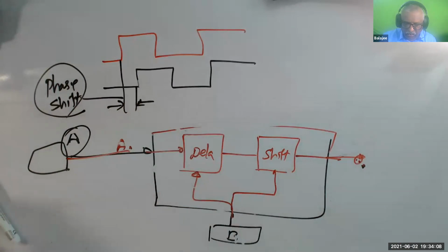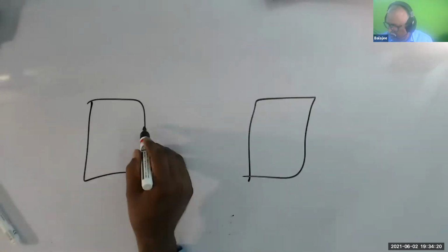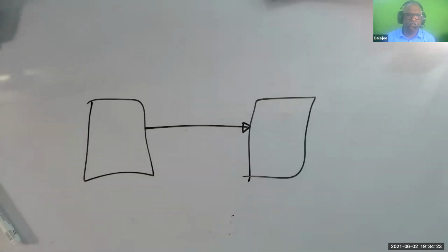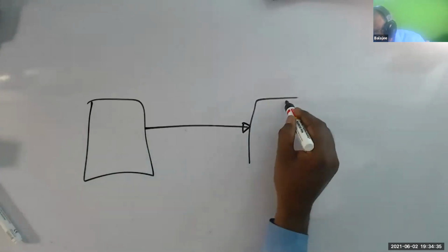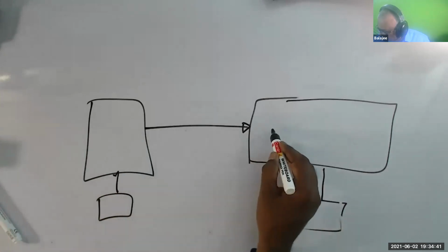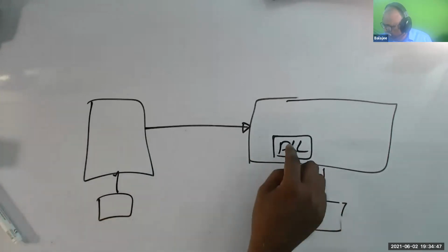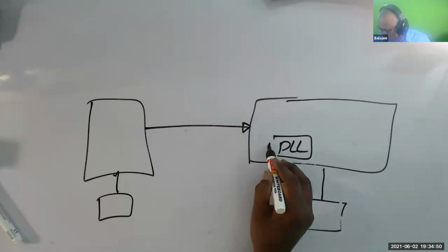But we know that it's fine. So when the A clock is coming, I could use directly the A clock itself. Why do I have to do these things? The problem is, in the communication, I wanted to use only one wire, but I want to use this wire as a clock as well as data. So what industry thought, first some time till the B guy detects a delay. This clock and this clock is coming, so this guy is detecting. That's called PLL, phase lock loop. That means that he is locking the phase with this guy. And they call this digital phase lock loop.